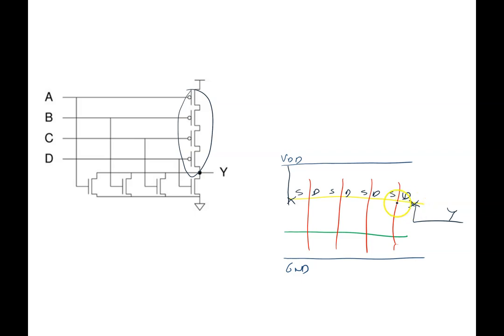Y, the function Y. Now I have to start with the source, then this has to be drain and drain, and the remaining is source. Now this needs to be same, and then I got drain, drain, and source. Again, you got 2 in parallel, another 2 in parallel. Now I know that these sources are going to the ground, and then drains are taken to the output Y. Now you've got the representation of a 4-input NOR gate.